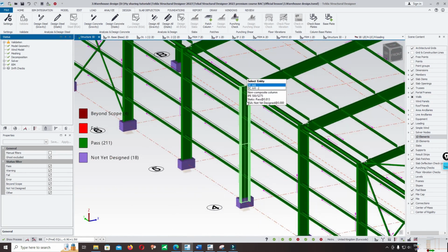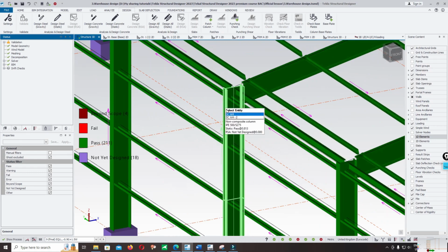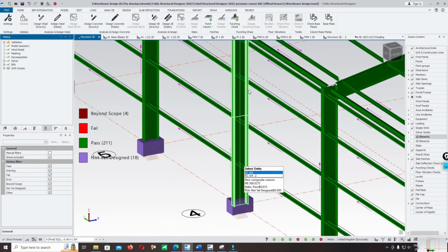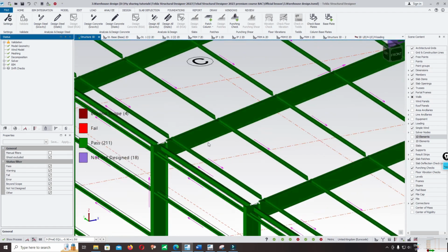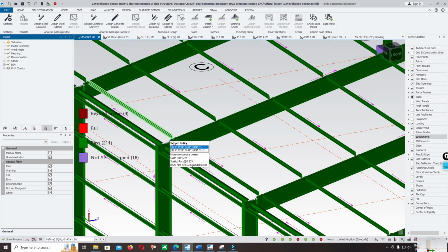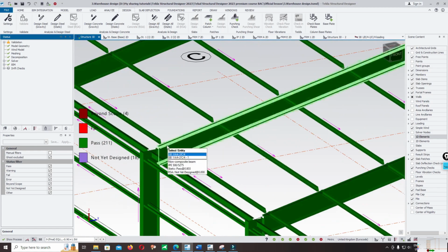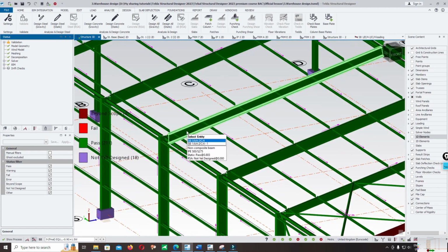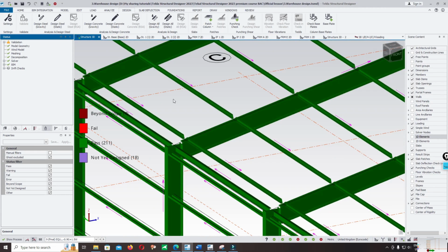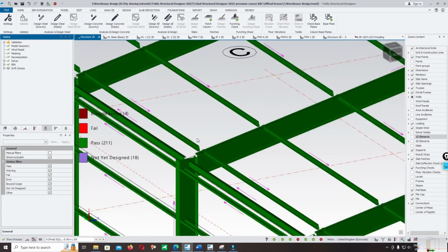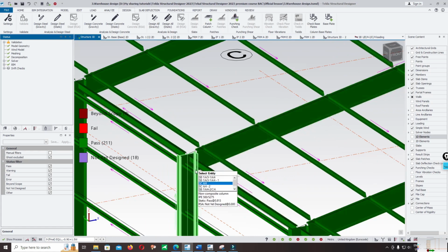Use the same approach. The best location to add restraint is at the top, at the maximum bending moment, and for the column we also add the torsional restraint at the tension face of the member. So for this rafter at the intersection with the column, the maximum tension moment is at the top, so you must add restraint to connect from the purlin to the bottom of the flange, and on the other side we do the same to add restraint at the compression plane.